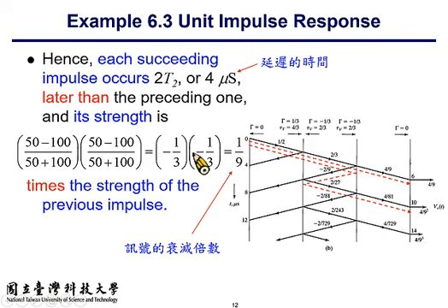And the transmitted or reflected signal may produce follow-up transmitted and reflected signals. So you can trace the bouncing diagram to identify fundamental and higher order terms that may come to the right-hand side and the left-hand side of the transmission line.